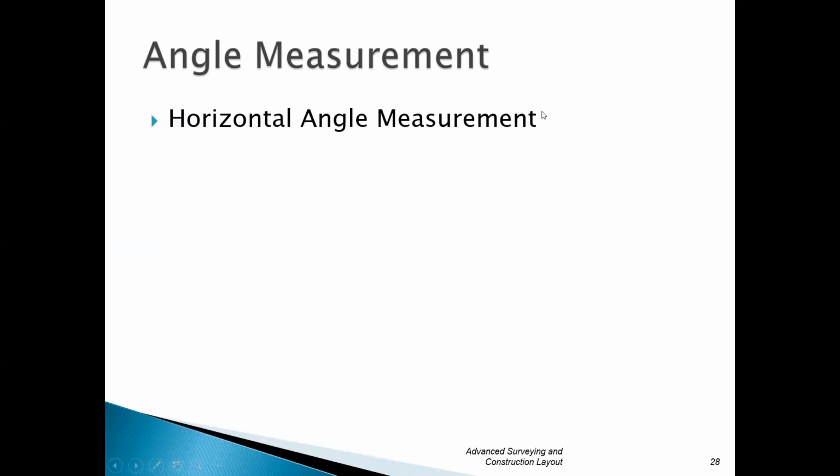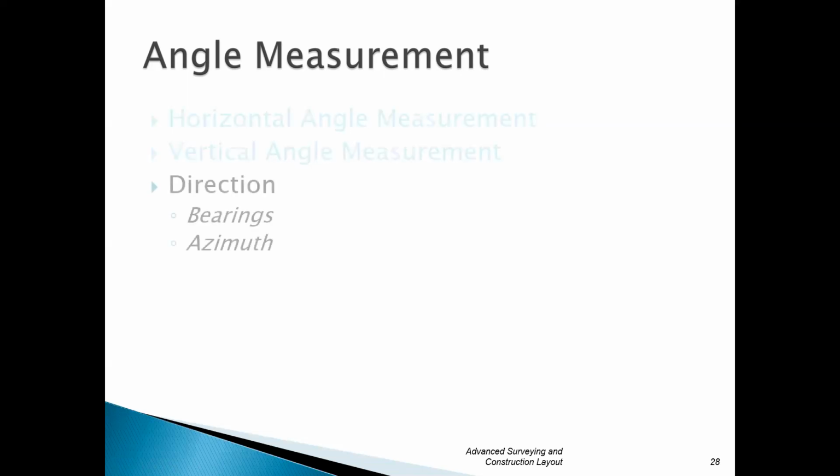We're going to be primarily using horizontal, either measurement or turning angles, one of the two. And vertical is used for things like trigonometric leveling when you're talking about elevation, or like we just saw, slope reduction. So it is used a bit for those kinds of things. But we tend to use the horizontal more than the vertical. And a lot of times the vertical is actually going on behind the scenes and we're not seeing it. So we have the vertical angle as well.